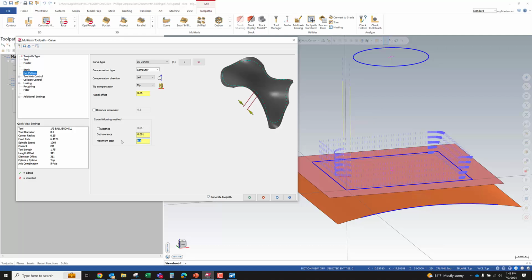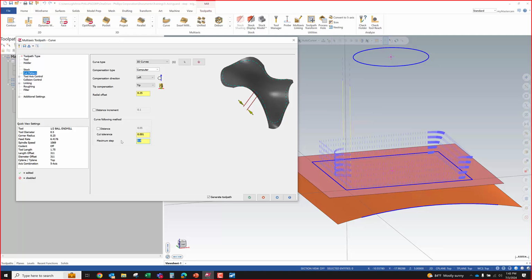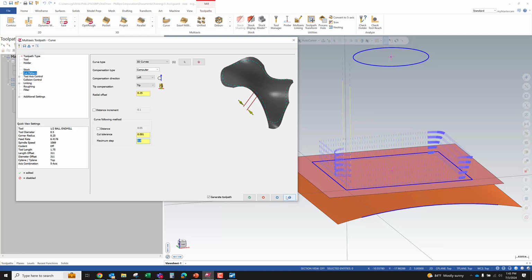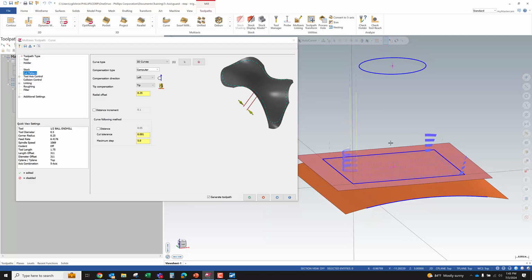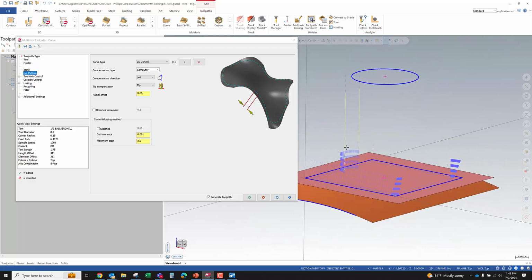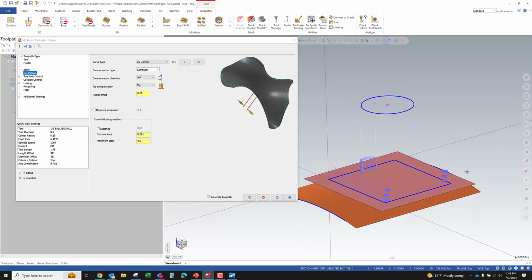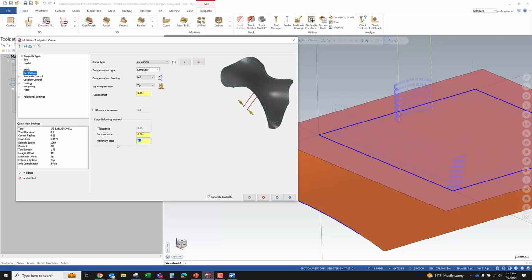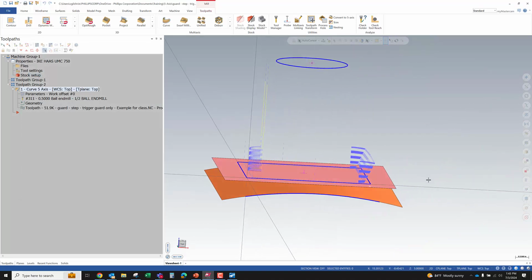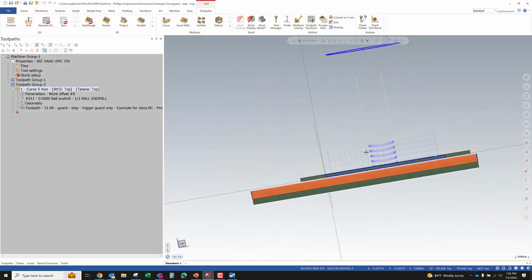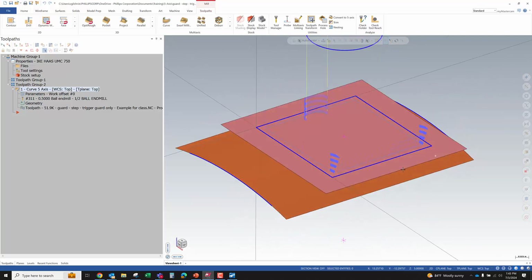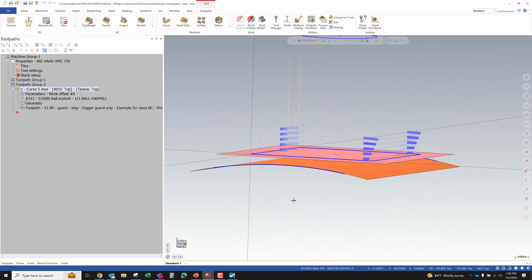So again, we played around with this. I think we tried a value of 10 and it was really wonky, didn't give us great results. Let's try 5. I mean, that works, but this is weird. Let's try going back to 3. There we go. So there's something magic about that 3-inch number with this particular path that's giving us these good results.